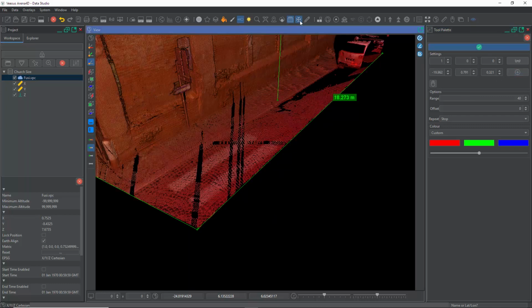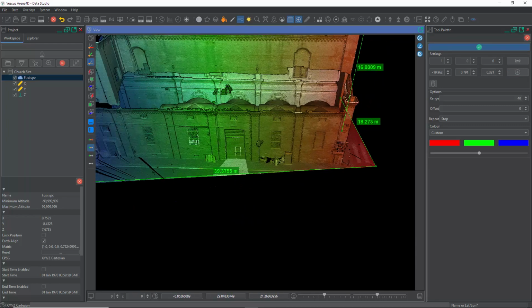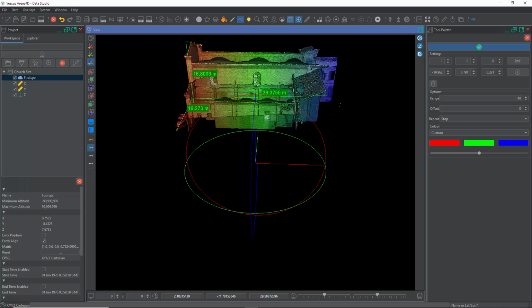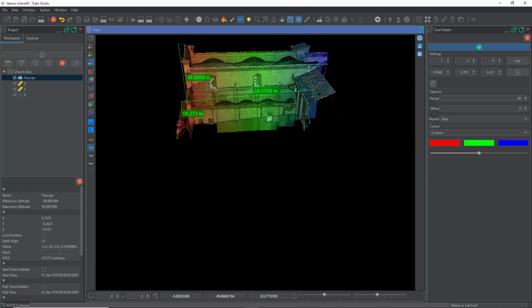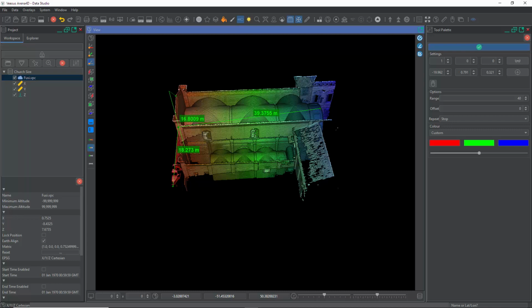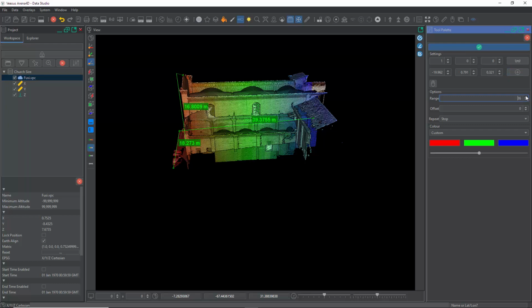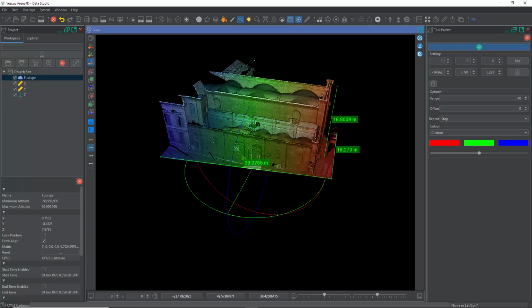Snapped point was turned on, so it snapped to this point. It's very useful to have that set first. And as you can see, we now have a 40 meter range going from red, this edge here, to 40 meters to this side here. Again, the options for doing repeat and the sizes all apply as shown in the Z-axis I just showed before.